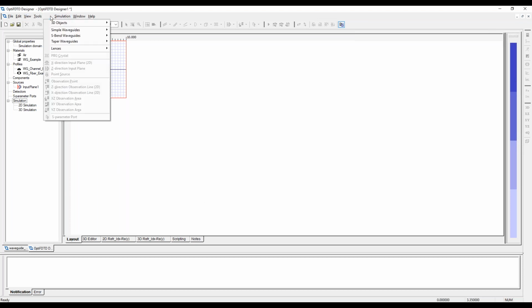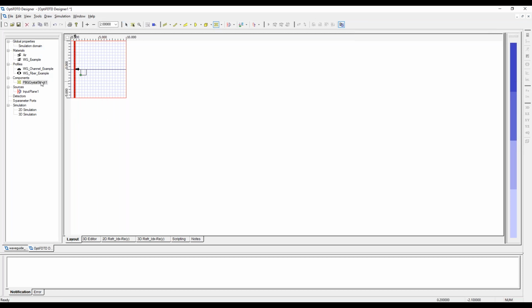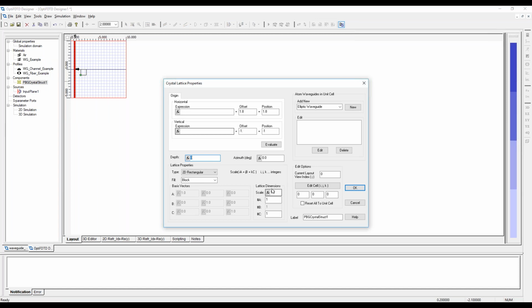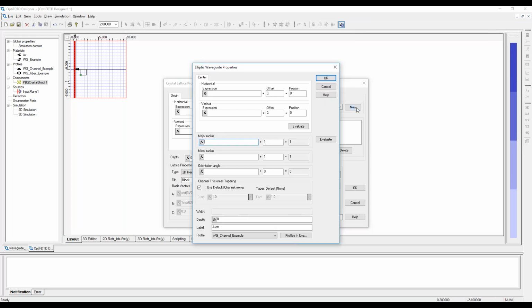And then I'm going to draw the photonic crystal structure right here. The pitch, or periodicity, was 1.24 microns. I'll just give a couple of elements so you guys can see it. It's got a hexagonal structure. And they are basically circles, so I'll add a new type here, make sure it's a waveguide channel, and the radius was, I believe, 0.403 microns.